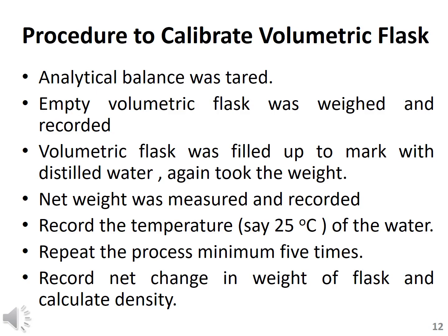Then calculate the net weight and record the temperature of the water, and repeat this process at least 5 times. For all the attempts, you need to record the net change in the weight of the flask and calculate its density.